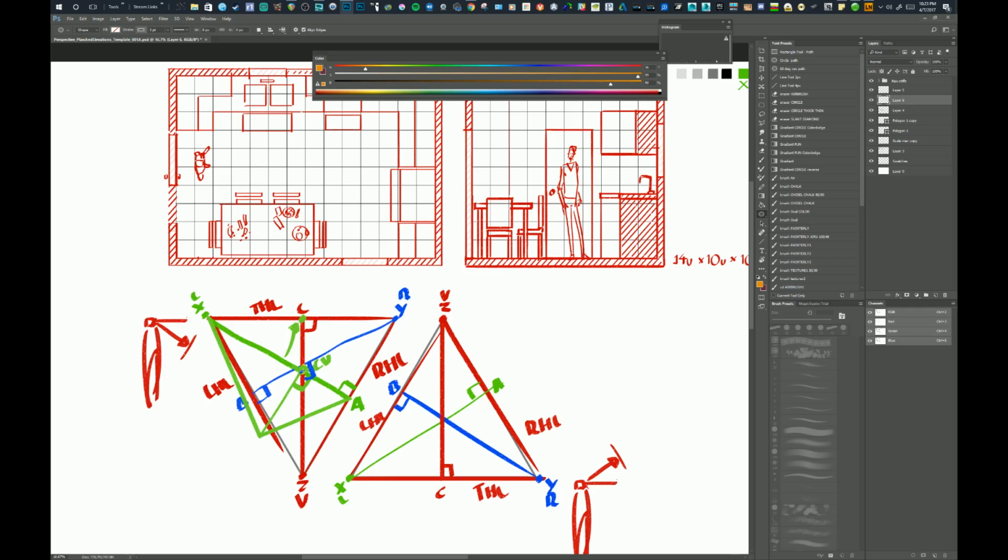So we're starting from the center of vision, and then we're going outward in a perfect circle. I don't know if you can see this, but I'm dragging out from the center of vision, making sure that the circumference of the circle meets halfway along the line that I'm scrubbing against. So here's the station point. I want to make sure that this circle meets halfway between the station point and the center of vision.